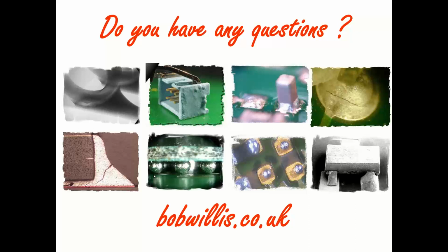So again, that's perfectly feasible. I've done that once myself quite a few years ago, and that clearly demonstrated it was flux, because I could do a comparison between the flux used in production and the flux within the failed sample. We could do an IR scan, compare the peaks of that scan, and show that it was exactly the same material. So it wasn't guessing that it was flux. I could prove it was the same material the company was using.